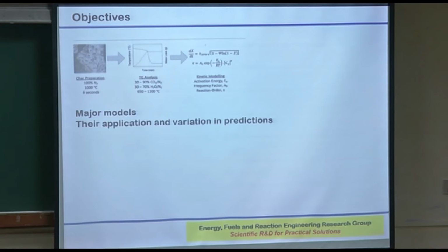Here in this case, let's see what she did. Let's keep in mind that the two reactions that she was looking at, one is carbon dioxide gasification, a gas solid reaction, of course endothermic, and the other one is carbon steam reaction, again a gas solid reaction, endothermic. One produces only carbon monoxide, the other one produces a mix of carbon monoxide and hydrogen in 1:1.